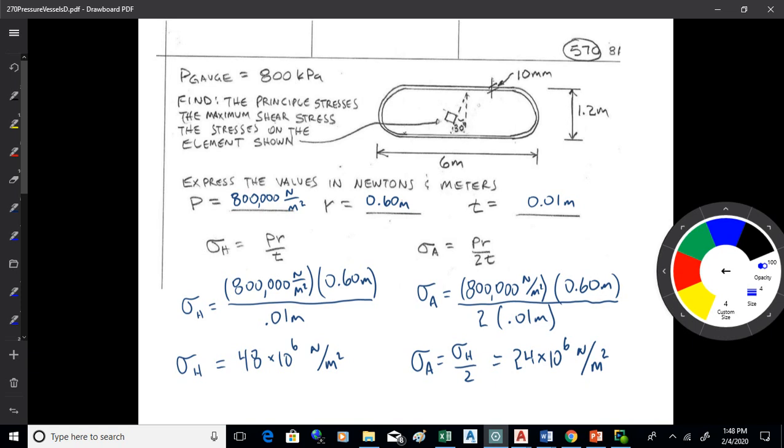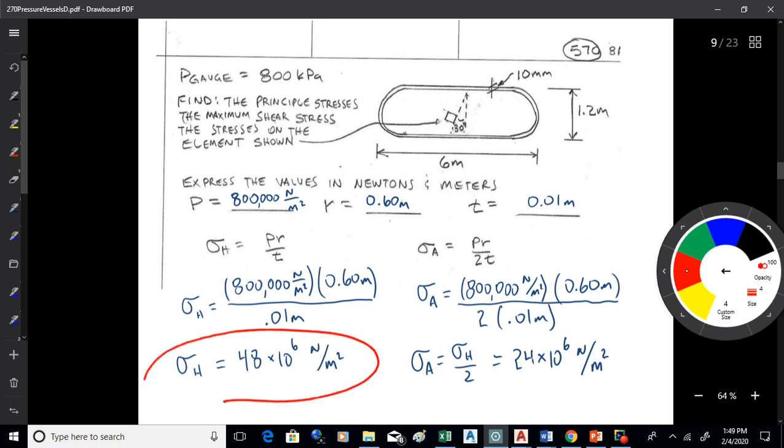So on these pressure tanks, you just find the pressure, the radius, and the wall thickness, and you plug them into the two equations on the formula sheet there. On the front lower right, equations 61 and 2. All right. But let's do a little bit of biaxial stuff here. Now these are principal stresses, so if you're going to design this tank, that's the normal stress you're designing it for right there. Okay, that's the biggest normal stress, so that's what I would call the design stress. That's the biggest one.